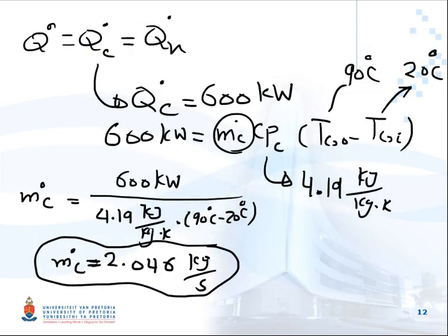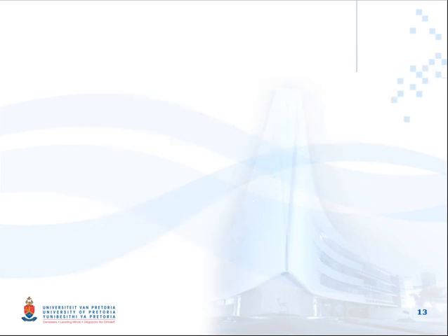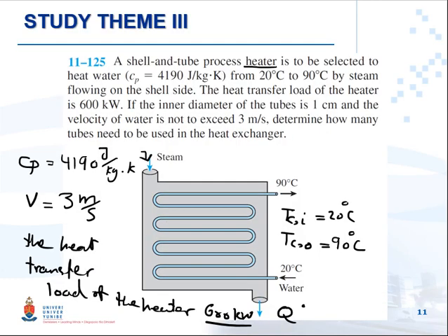So basically AS is the problem here. But we have an issue here, because if you look at that, how are we going to find it? We need to find U, which is the overall heat transfer coefficient. After we find U, we have the Q dot, so we need to find delta T Lm for counterflow and the correction factor, but we can't use the LMTD method.